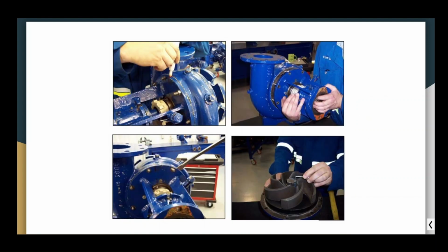When I was an operator, my task was also to disassemble and assemble the pumps in order to change a stuffing box to prevent leakage, because there was leakage in this connection and we needed to change it with my coworkers. We did the job, and there is obvious information for you on how to disassemble. I showed pictures. This is an open type of impeller. We changed these stuffing box elements.